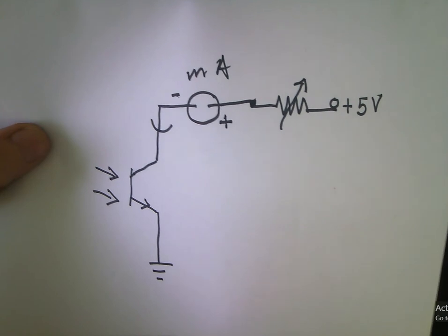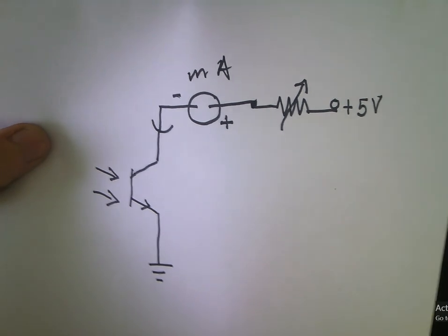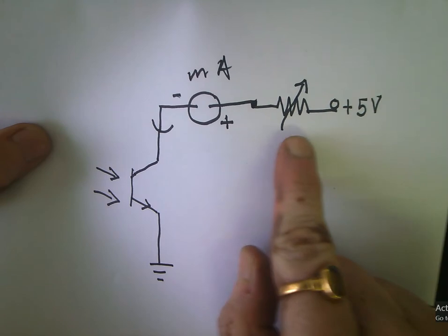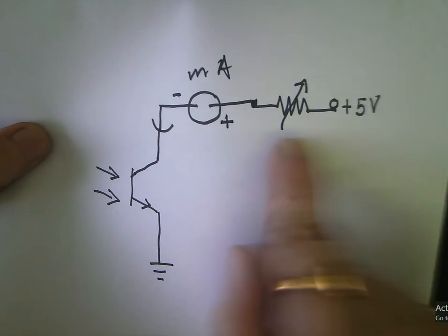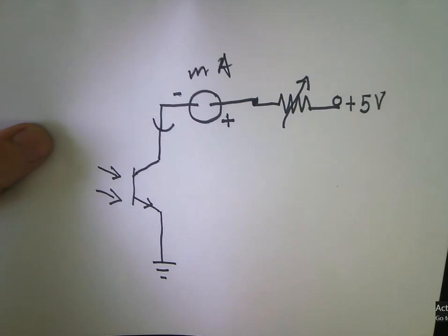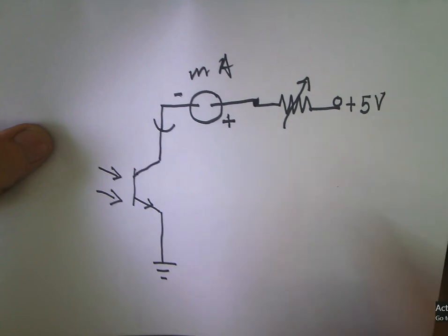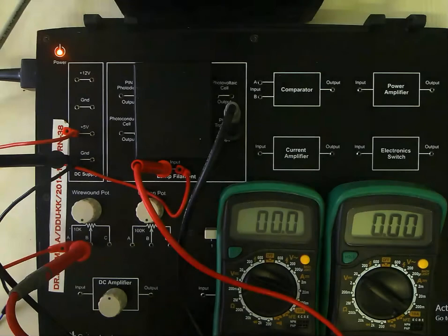This is very important to understand. Therefore, in order to have a control over this voltage drop, always use a variable resistance here. Whenever you are doing a project of photo switches like that, you will come across the problem with a fixed value of resistance. So it is always better to use a variable resistance over there.